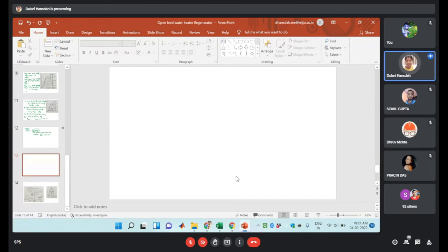That's why sometimes we are using the binary vapor cycle. Okay, so what is the name? The binary vapor cycle. Binary vapor cycle means here we are using two working fluids. Because of the certain drawbacks of water as the working fluid, we are using two fluids so that the cycle temperature will increase.